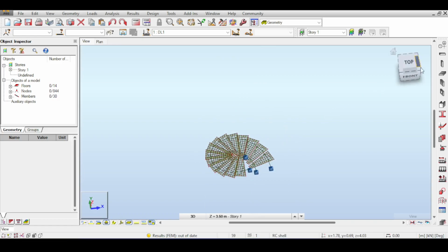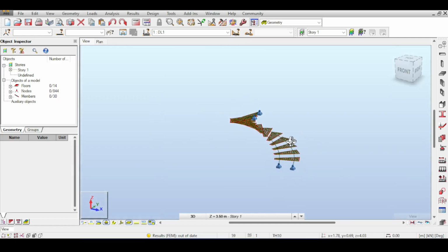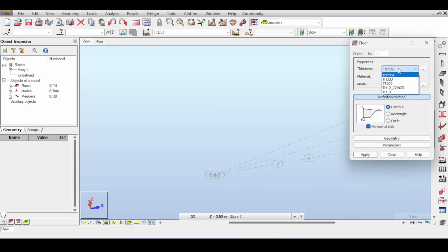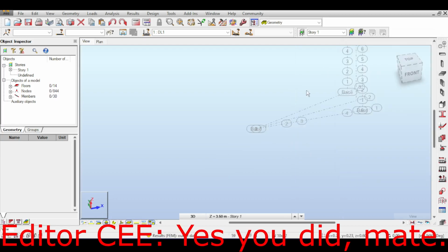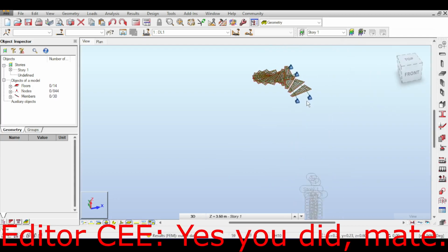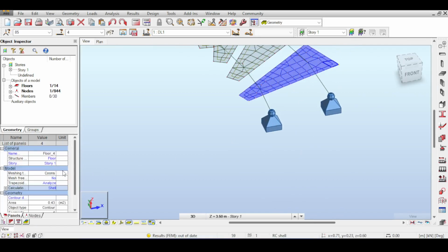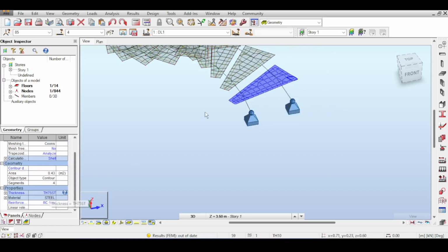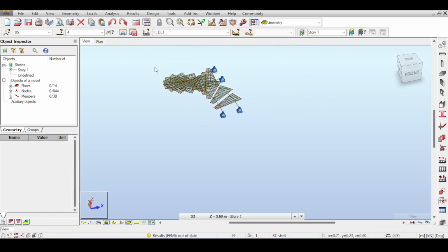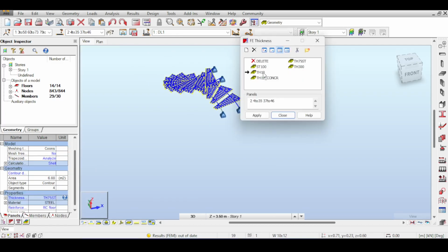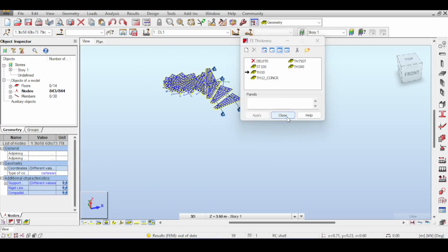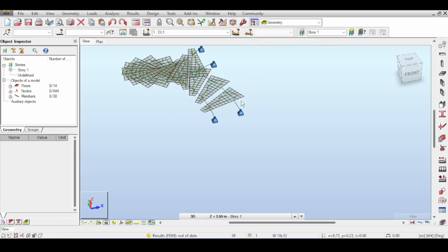I may or may not do this in the next video because I'm just gonna leave some stuff for you to think about. So I'll just select this. Wait, thickness 75? Did I mess up my thickness? Let me just check. Let's select this. What's your thickness? Thickness 75. Huh. I messed up my thickness. Well, that's easy. Select everything, so let's fix that. Tick, tick, and done. Now we have our correct thicknesses, right?